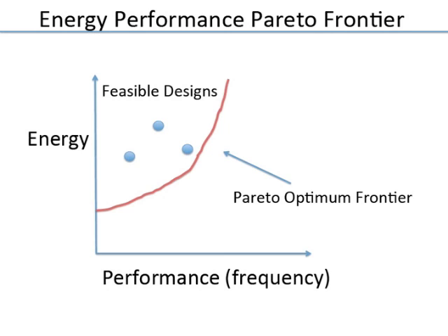For example, if you decide on a particular architecture and microarchitecture, and you find the critical path, then you can model the critical path's delay as a function of supply voltage, restricted to that design, to find the right voltage. With the previous equations, we can model energy versus voltage and frequency versus voltage, and explore that in an analytical way.